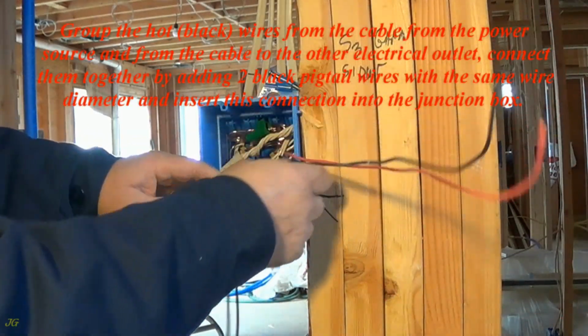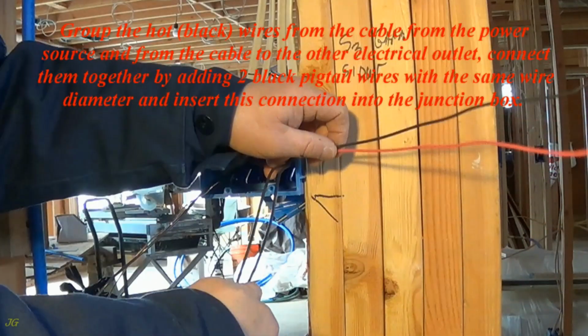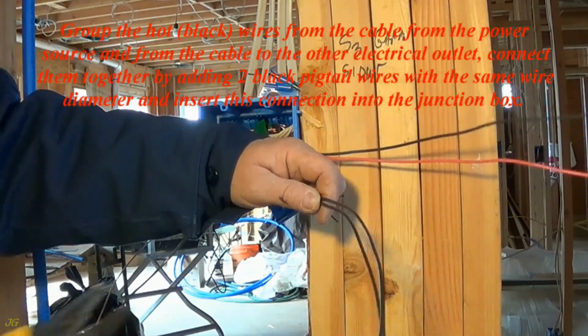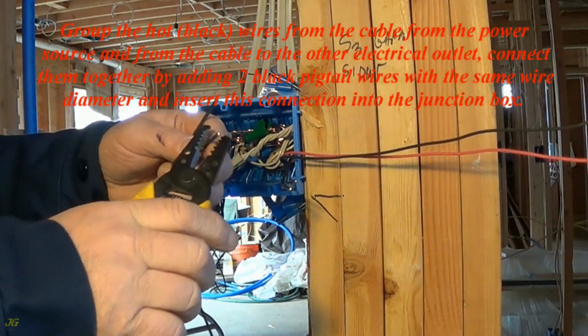Group the hot, black, wires from the cable from the power source and from the cable to the other electrical outlet. Connect them together by adding 2 black pigtail wires with the same wire diameter and insert this connection into the junction box.